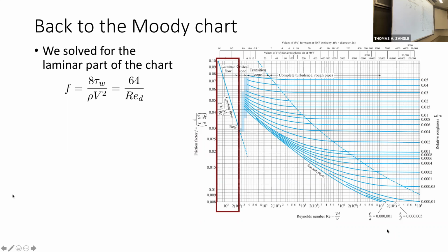It can definitely vary. If you have new steel versus old steel, you're going to have different roughness, depending on corrosion and pitting and that kind of thing. So it can vary over time, even within the same material. But typically that would be known, or it would be measured. There might be a handbook of values at a company for their own characterization.